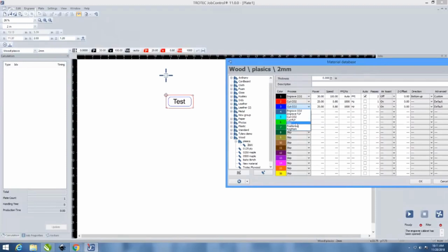What we're doing when we say kiss cuts is we're using the cutting with CO2 method, but we're just using a very low power here, very low, and high speed. We just want it to kiss the surface. So we can do, let's say, 10, and like Lev said, because we're not really cutting anything, we're going to use a higher speed, kind of like what we were doing within the engraving up here, and that's just to mark lines on our material. I just thought I'd cover that.